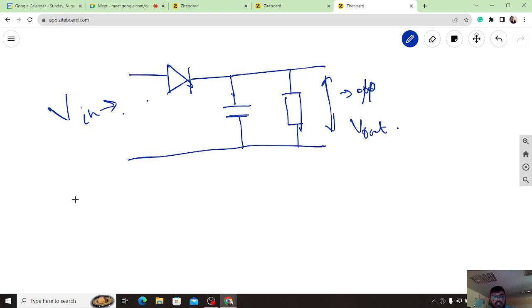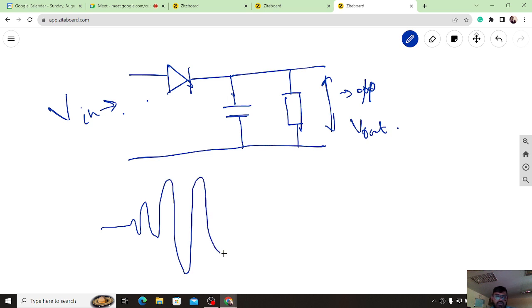Basically, if a carrier frequency is coming here like this, what will the diode do? At first this peak, when this is positive voltage, only then this diode will let it pass. So basically it goes here, and then this capacitor is getting charged. When the capacitor is getting charged slowly, it is just taking the peaks, and then slowly it is again discharging. So it actually finds out the message signal that is encoded in this carrier frequency.